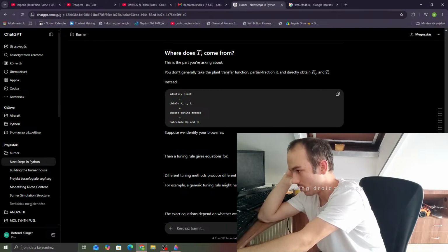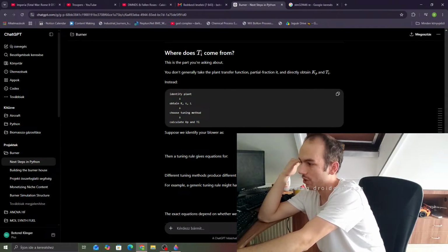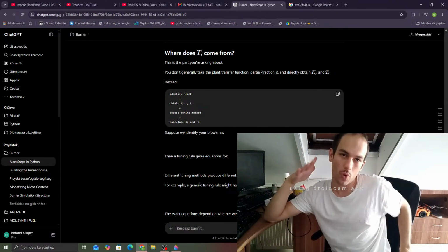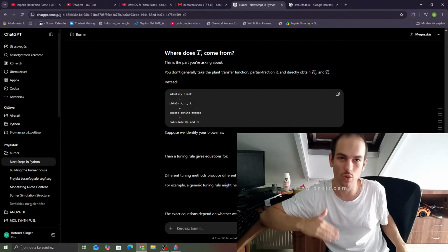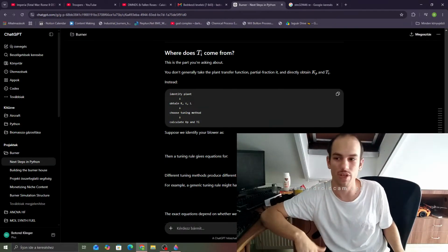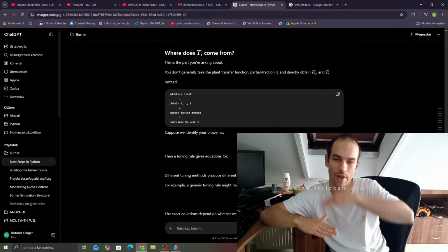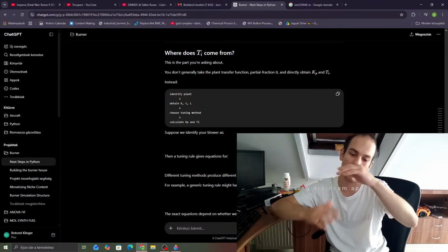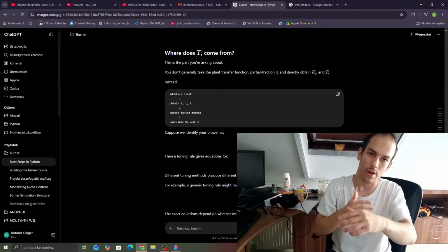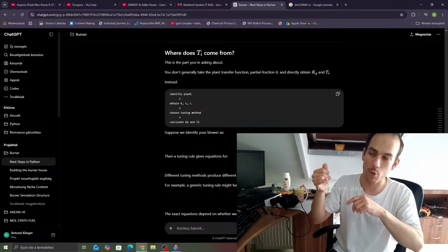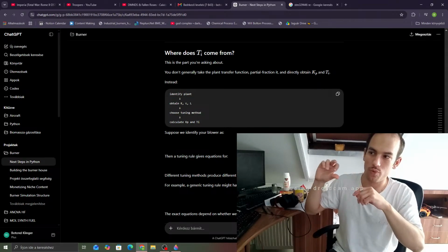So it contains that, and you need the integral term. The proportional is going to be proportional to the change needed. The integral is like a memory: if you overshoot by a little or undershoot by a little, it takes these terms and adds them to its memory, and based on the memory, if there's still change, it adjusts.